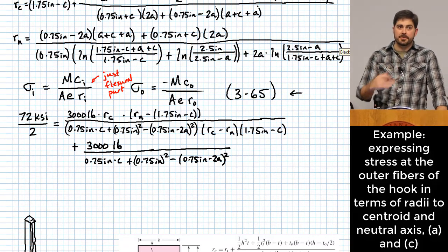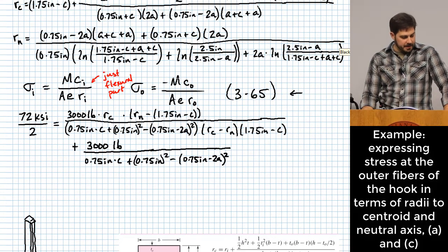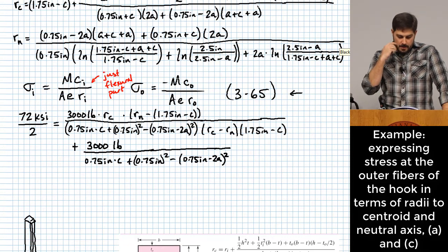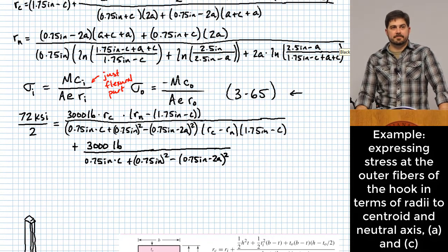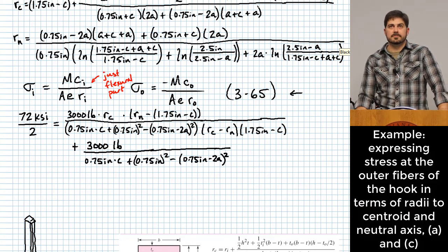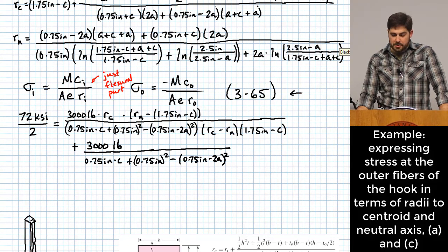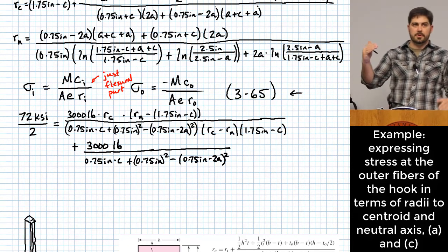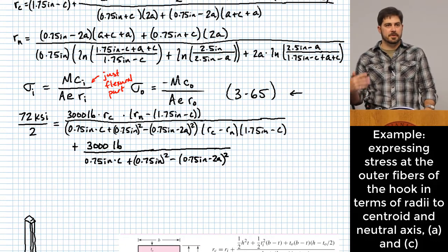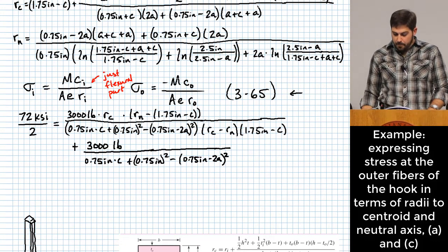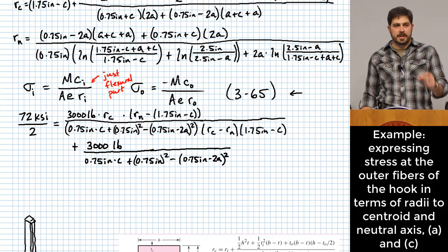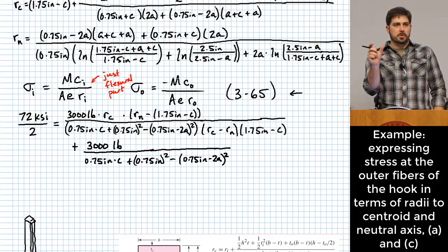Okay, the stress on the outer fibers. And the presumption there is that that's going to be in compression, right? Although it doesn't necessarily have to be. Why not? Our presumption here is that flexural stress is going to exceed normal stress. And it usually does, in many of our cases anyway. But it is possible that we could end up with a larger just axial stress happening here than the flexural component.